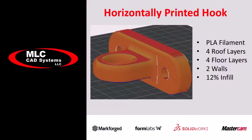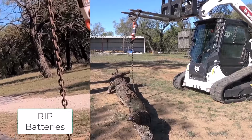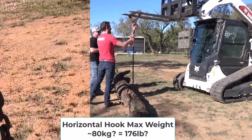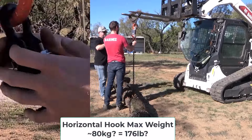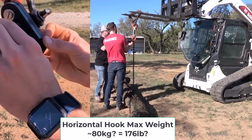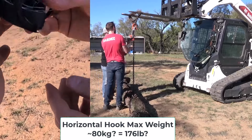Test number 2 was the horizontally printed hook this time, still with PLA filament, 4 roof, 4 floors, 2 walls, and 12% infill. And the batteries for our tester died in the middle of this one, but we were still able to get a pretty close estimate. Right around 80. Okay, 80 something. So you can see this one broke a little differently, and it actually broke along the hook. And that's probably because this is a really light infill. I think it's 10 or 15% with only a couple of walls.